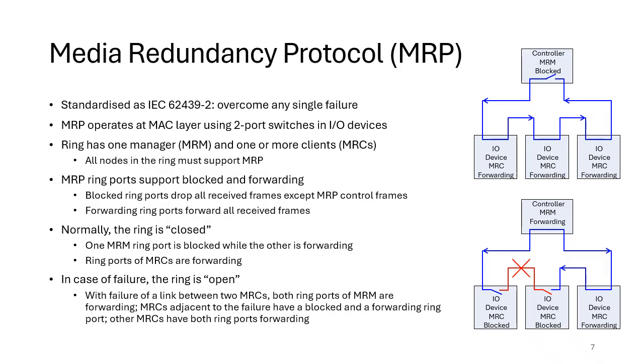Now the eagle-eyed here might point out that your controller is a single point of failure, and in this architecture, yes it is. A single controller could fail, and then you wouldn't have control of your I/O, that's true. So this is where we can combine media redundancy protocol with system redundancy, where we can have CPU redundancy, and I'll come on to that soon.